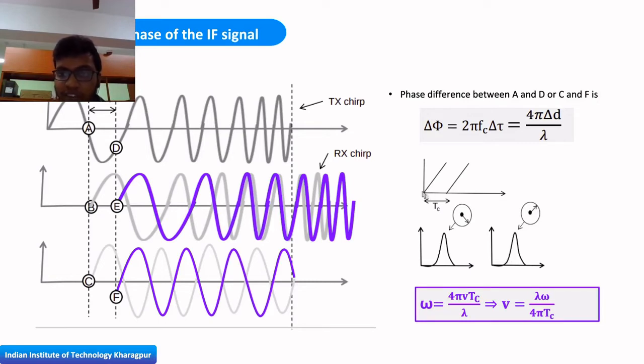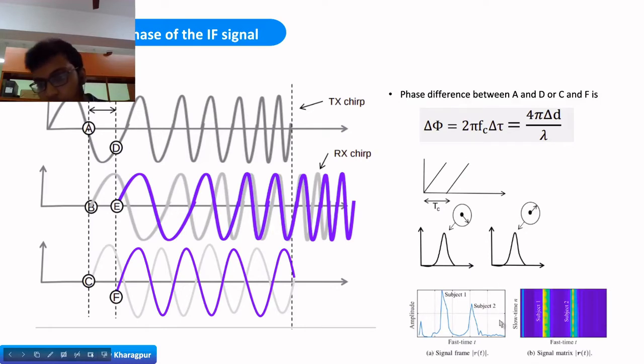Here you can see that FMCW radars basically have a frame. In that frame they send multiple chirps. If you apply the range FFT on top of the first IF signal, you will have this frequency spectrum and you will be able to easily calculate the range profiles. In a single frame you are sending multiple chirps, say n chirps. For these n chirps, if I start filling in the corresponding phase differences where the object is located in those range profiles, I will have the corresponding movement of the object. So this plot is important, because it gives you an idea of where the object is located and the velocity at which the object is moving.